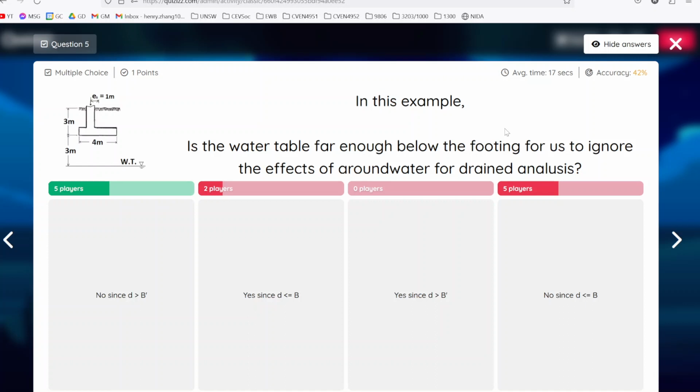One other thing that's happening in this particular question is that there's eccentricity. Okay. So eccentricity is basically load offset. If your load is being applied like that on a footing, that's the center of the footing. Your eccentricity is your offset, like that, right?